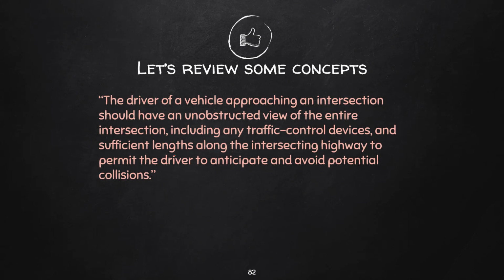So as a review of the concepts, the driver of a vehicle approaching an intersection should have an unobstructed view of the entire intersection, including any traffic control devices, and sufficient lengths along the intersecting highway to permit the driver to anticipate and avoid potential collisions.